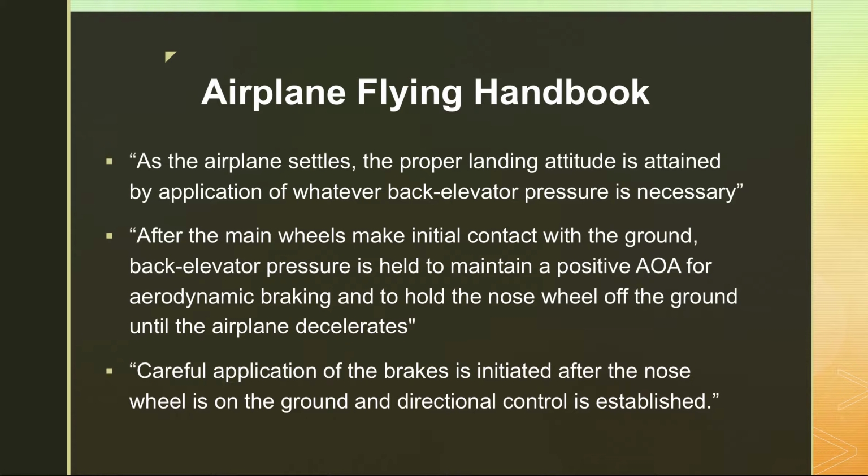As the aircraft slows down, it wants to nose down, and it wants to put the nose wheel back on the ground. The Airplane Flying Handbook says that you should keep applying back pressure to try to keep that nose wheel in the air. All right, it looks cool. It's better on the nose wheel.